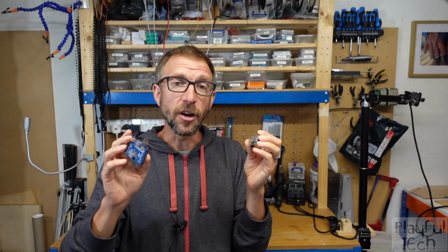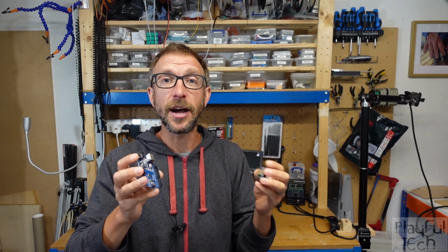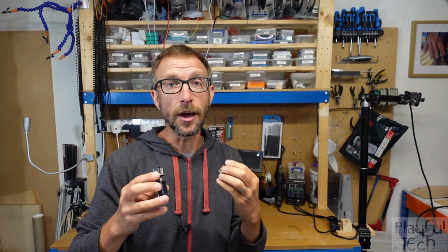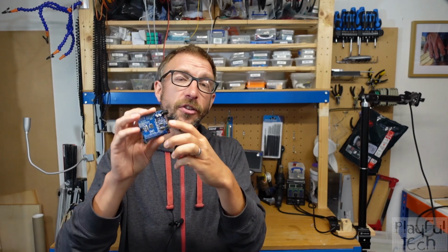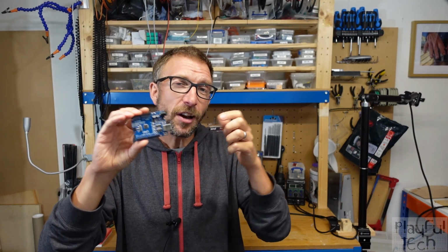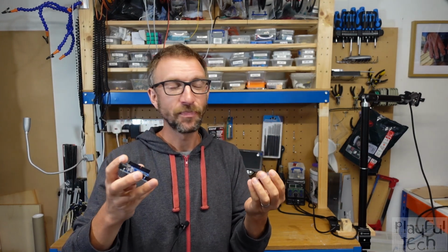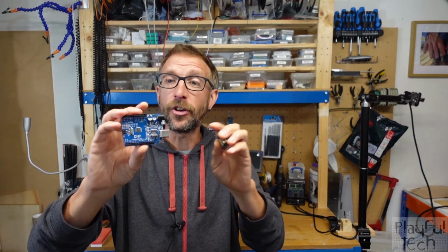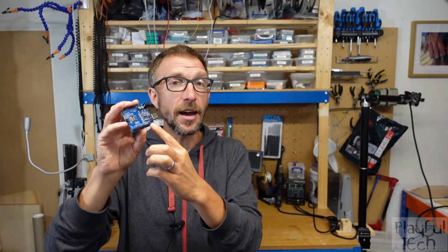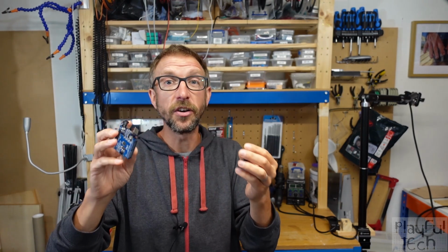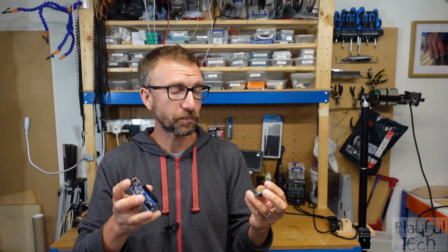Now, most GPIO pins are digital, so they can have one of two discrete values. They're either high or low. And that definition of high and low relates to the voltage at the pin relative to a somewhat arbitrary 0 point, which we call ground. Now, ground is also one of the pins that's exposed around the edges of the board. Sometimes you might have several ground pins, which are provided for convenience. They're all connected together, so they're all interchangeable.